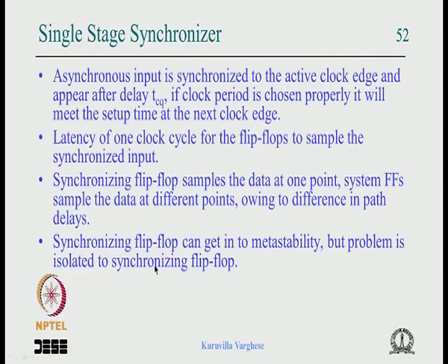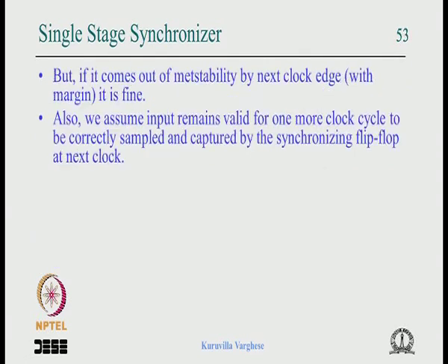Now the final analysis is that the synchronizing flip flop can get into metastability, but the problem is isolated to the synchronizing flip flop. We are assuming that before the next clock edge it comes out of metastability, and we also assume that the input remains valid for one more clock cycle to be correctly sampled and captured by the synchronizing flip flop in the next clock.